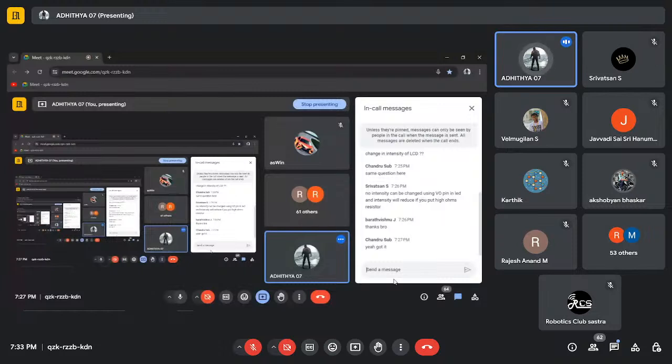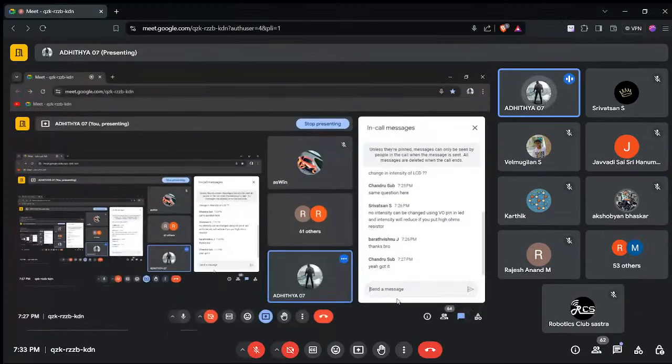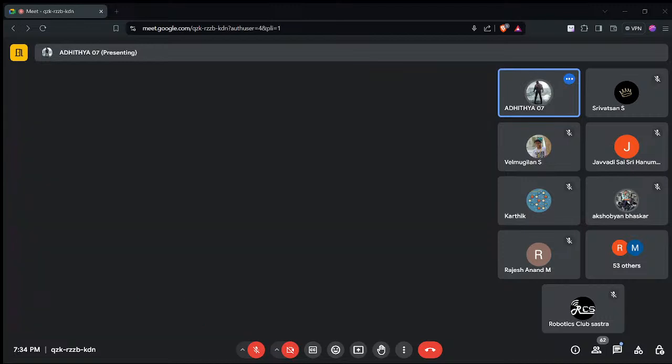When you give input as 1, there are 4 switches here. S1 is on and S4 is on, which makes current flow from the positive to the negative of the motor, and the other 2 switches are off. When you give input 2, these 2 switches get opened and S3 and S2 get closed. Now the current travels from the negative to the positive of the motor, making the motor rotate in the opposite direction. So this is the simple thing about this circuit.